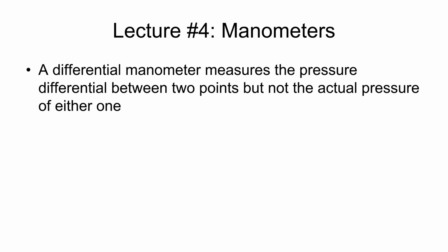So that's how we would solve an open-ended manometer, and that's a pretty common one that we would use where we're just trying to solve for the pressure at a specific point in a system. Commonly, we'll see that a lot in HVAC equipment where we just want to measure what's the pressure at a point in a piece of ductwork or through a unit.